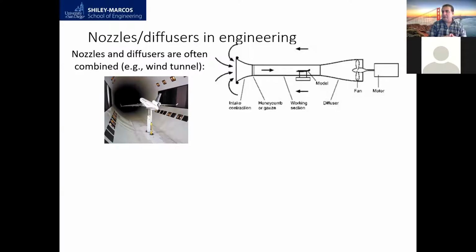If you place a propeller inside the air duct, and then if you have a vane anemometer, you have meters, you can directly measure the flow inside the air duct. But in order to have a fully developed flow, we need to put a strainer or some kind of cascade type of mesh, so that the air that goes through it becomes fully developed before it hits the cascade blades that we're going to measure the angle of attack loss.